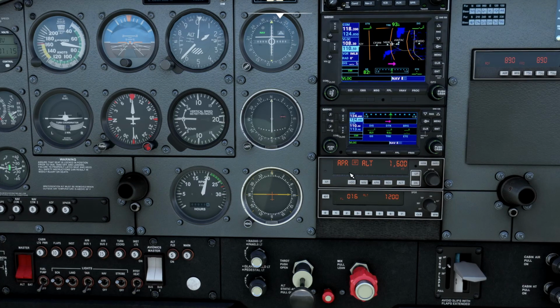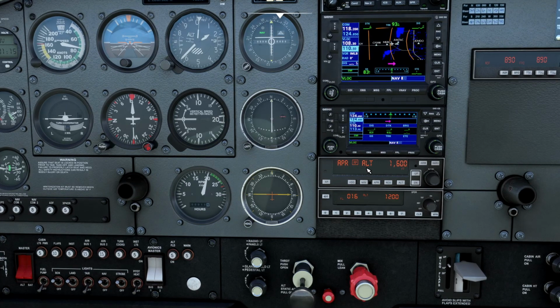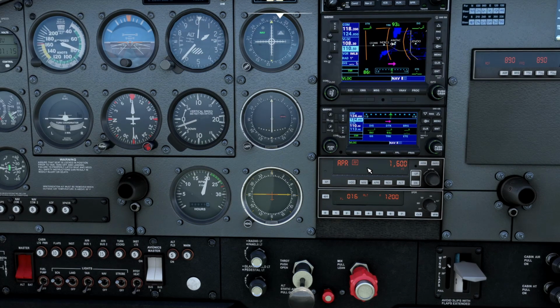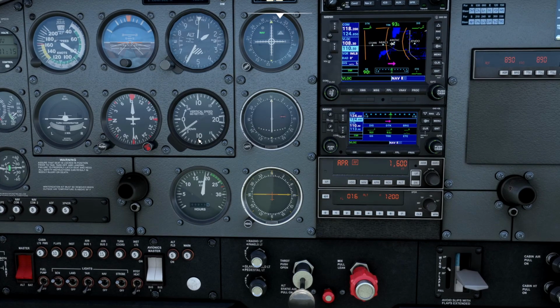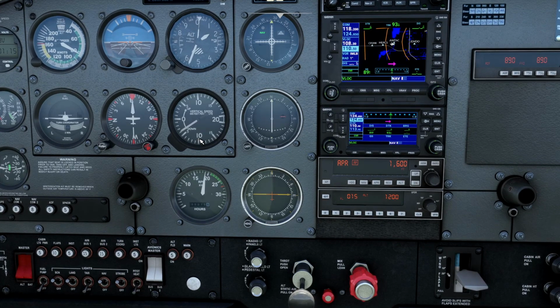So as the autopilot intercepts the glide slope, the pitch mode display will go blank. I don't think this is how the system is supposed to operate on the real system. I believe it indicates GS to indicate it's tracking glide slope, but you'll notice when it intercepts the glide slope, it will go blank. And we'll see it pitch down and start to track the glide slope. So you know it's tracking the glide slope at that point. The approach mode and the roll mode window stays on. So there it goes. It's pitching down. We do have to control configuration and power to keep it on speed, and then we just monitor the system and make sure that it's staying on the glide slope appropriately.